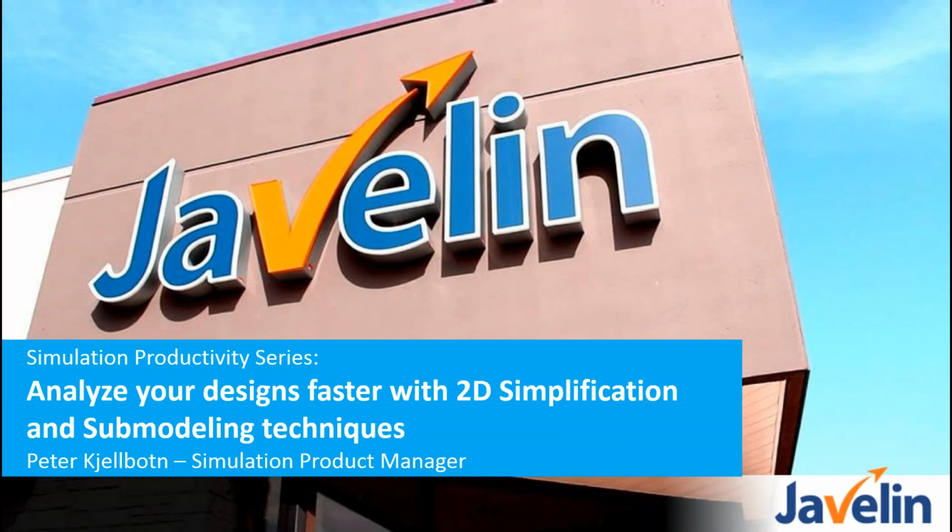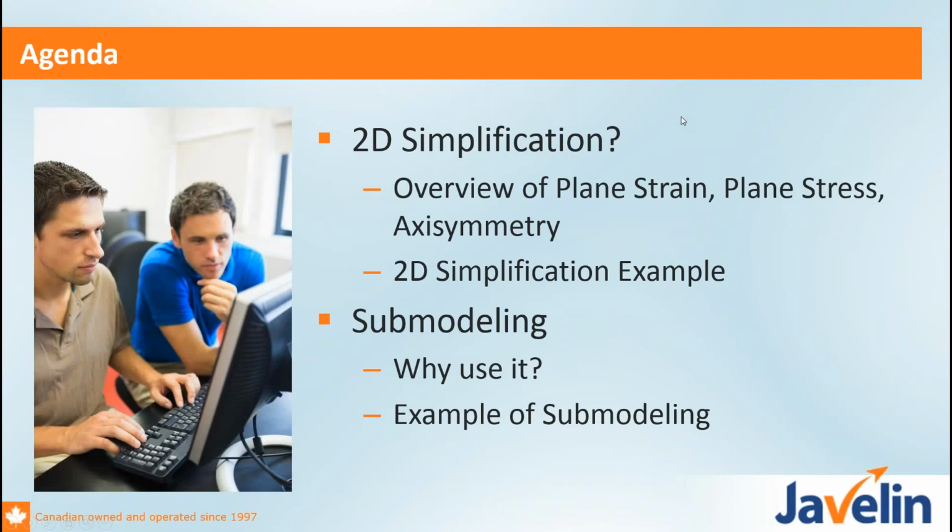So what we'll be doing today is talking about 2 new techniques. Well, they're not new, they've been around for a couple of years, but a lot of people really still aren't familiar with them. These 2 techniques are going to help you speed up your simulation and speed up your stress convergence. We're going to look at 2D simplification as well as submodeling. I'm going to hopefully show you exactly what those features are, how to properly set them up, and give you some examples of when they can be used.